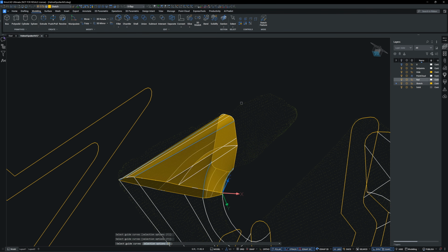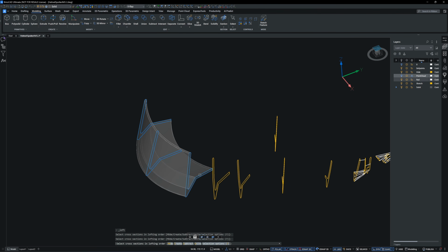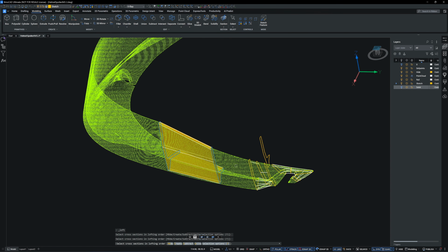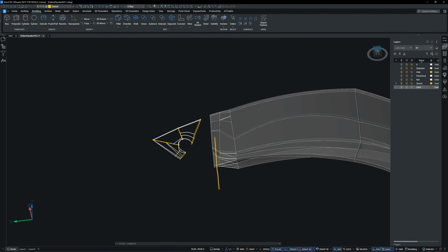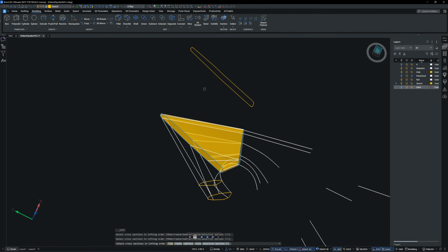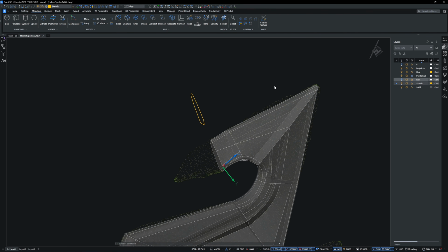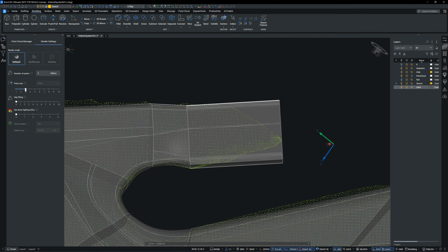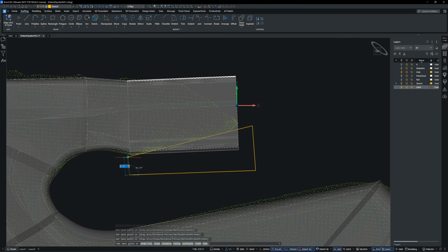This will be the final loft section. Since I have already tested all the loft sections, now it's time to create them for real. I have placed the created solid on a separate layer shown in gray. The sketches are on another layer in orange, so I can toggle them on and off easily. For the tip of the hook, I will simply extrude it and then cut it into shape using the sketches.